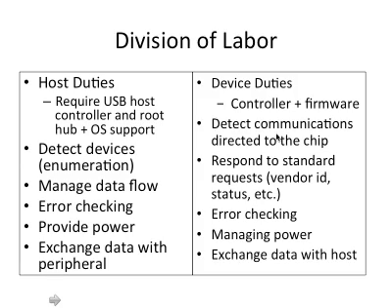On the other hand, on the device side, you will need, again, a USB controller plus necessary hardware or firmware. You will need to detect communications to the chip. And the device has to be able to respond to standard requests that are coming from the host side. For example, the request could be for vendor ID, status, etc. It will also need to do error checking, manage power, and exchange data with the host.